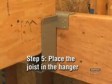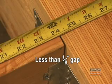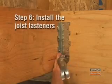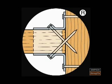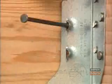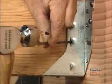Step 5 is to place the joist in the hanger. There should be less than 1/8 of an inch between the end of the joist and face of the header. The final step, step 6, is to install the joist fasteners through the side plates and into the joist. If you're installing a hanger with a double shear feature, install nails specified for the hanger, which can be 10-penny common, 16-penny sinker, or 16-penny common nails at an angle through the domes or tabs on the side plates. The nails will go through the joist and back into the header.